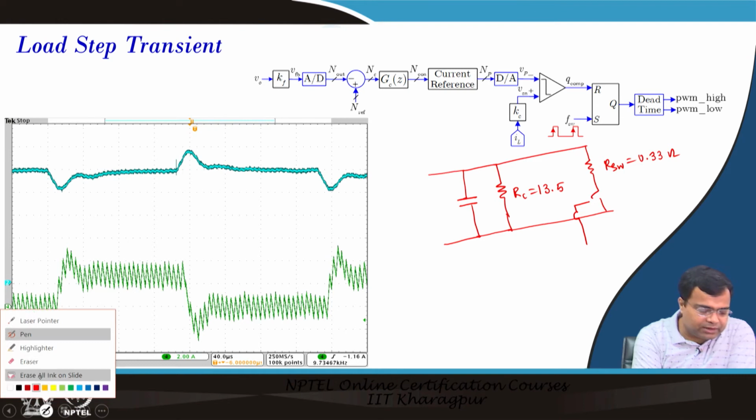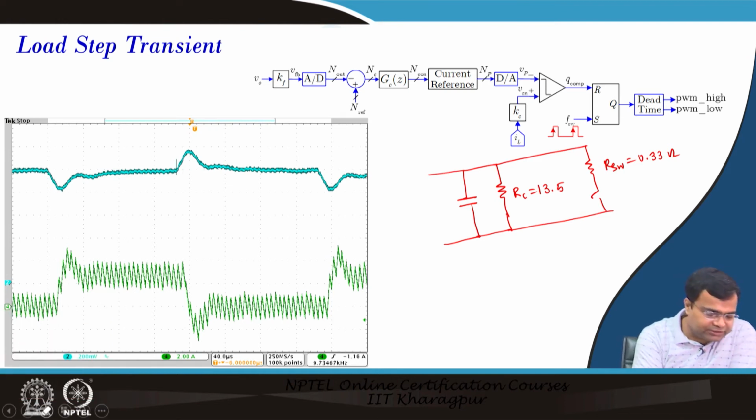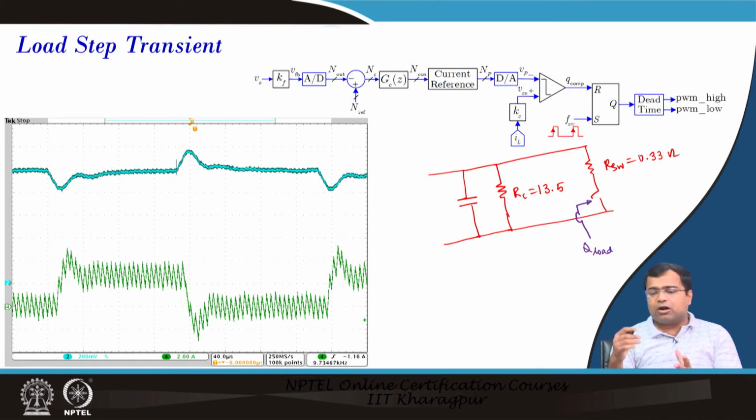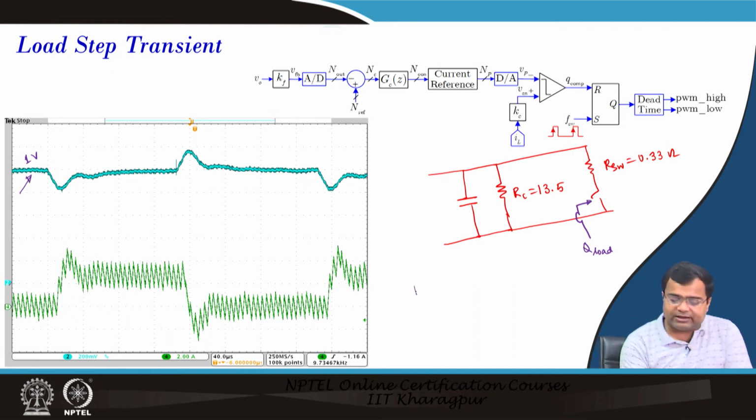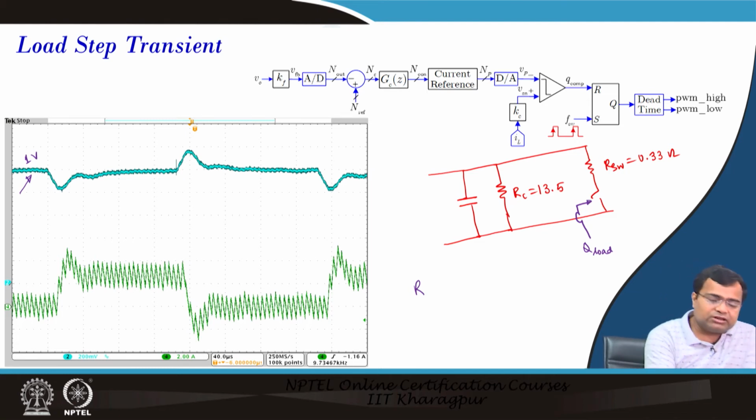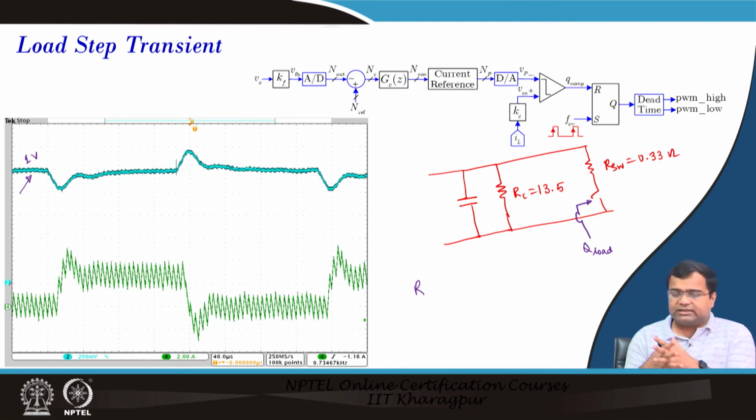We are considering one external load, a MOSFET to turn on and off. This condition is at 1 volt under lower load condition. The effective load resistance is either a simple RC under light load condition, or, under high load condition, a parallel combination of RC and RSW.